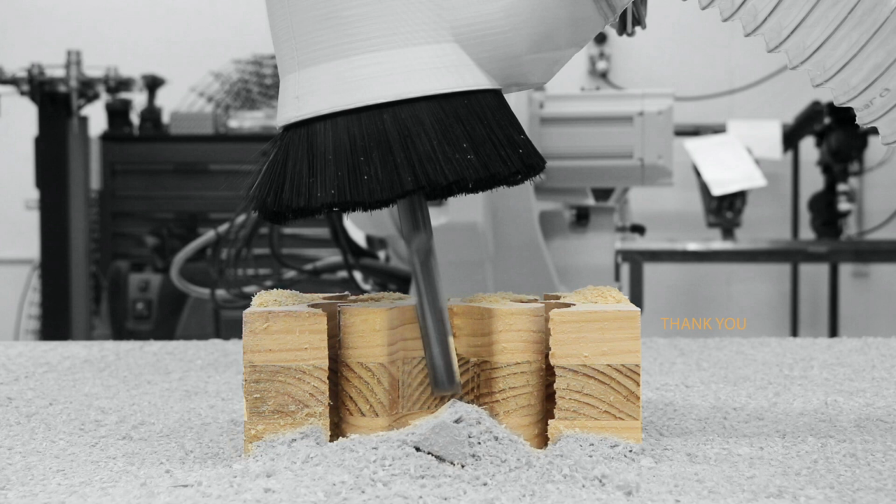The milling bit is rounded and has a much better time creating rounded shapes, therefore the fits are better. This does, however, reinforce the importance of tolerances. The robot will always find the easiest path, and that is usually a straight line. So, when creating a curve, there need to be many more targets in order for the robot to create a clean curve. These targets then need to be replicated exactly for each piece of the joint.